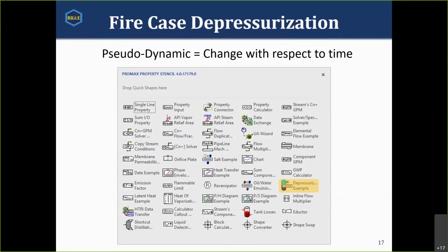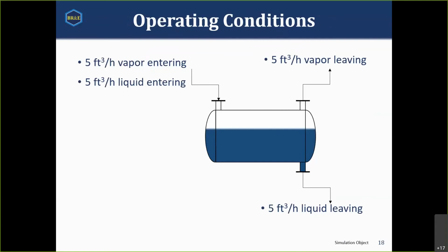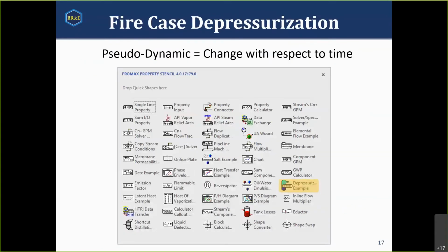It can also do a no energy input case, a full-on depressurization like we just did. It can also do fixed energy. If, for example, you've got a line heater or something equivalent, it can do that too. Now, something I kind of glossed over a lot last time, we're going to go into more depth, and that's how to create your relief scenario. When you have your standard case, your standard stream, you need to turn it into your vessel. You need to turn it into your pipe. You need to turn it into whatever it is you're depressurizing. And your stream doesn't really represent it.